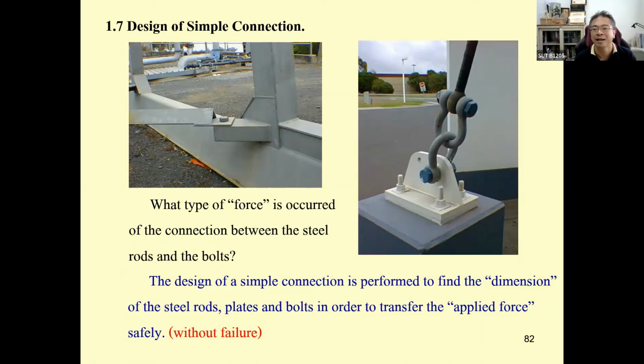What I'm saying is we apply the force like this, and then there is going to be a resistance force here, and that resistance force is going to produce shear between this. Since there are 2 shear surfaces, this one and this one, it is going to be double shear. In this one you pull the force like this. There is the bolt over here, and the bolt is subjected to one surface. This is going to be single shear.